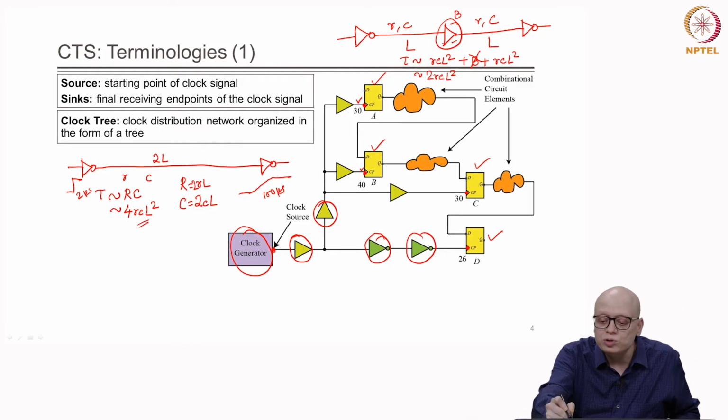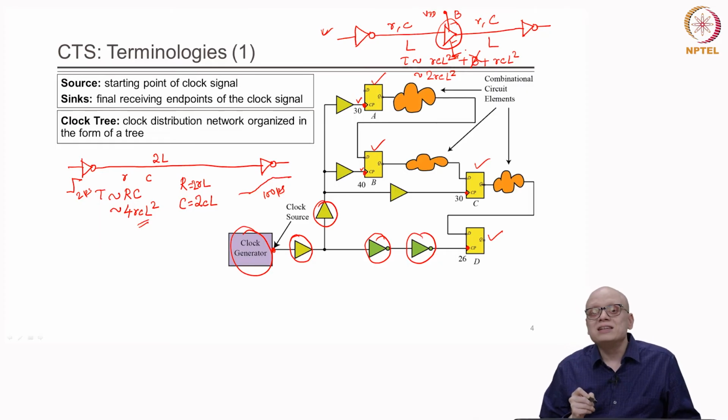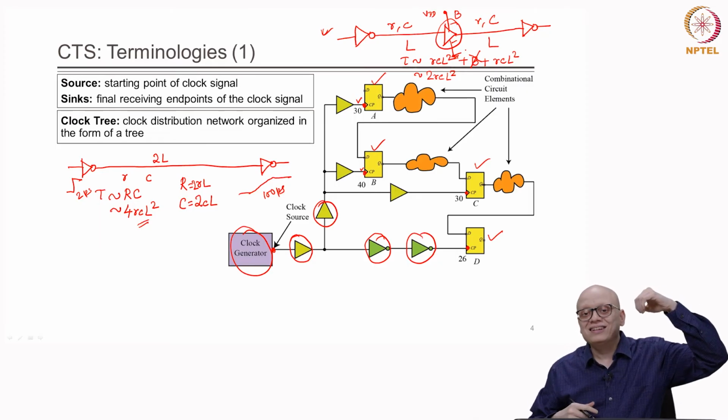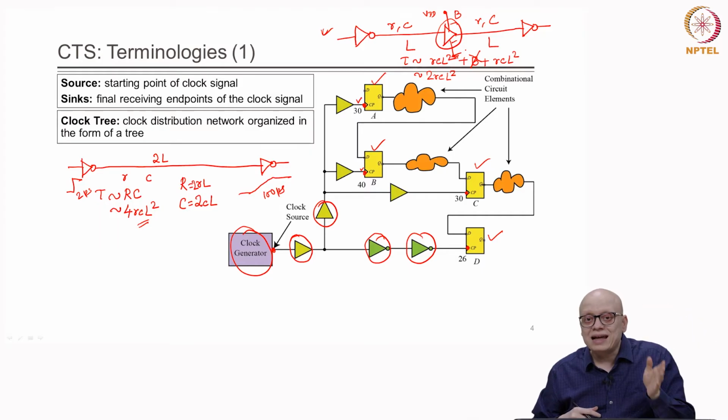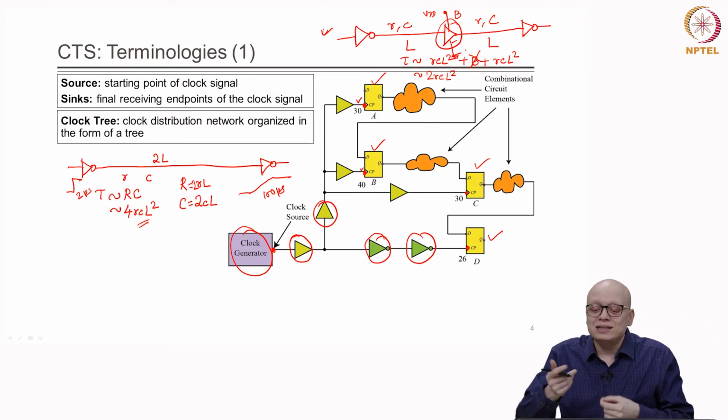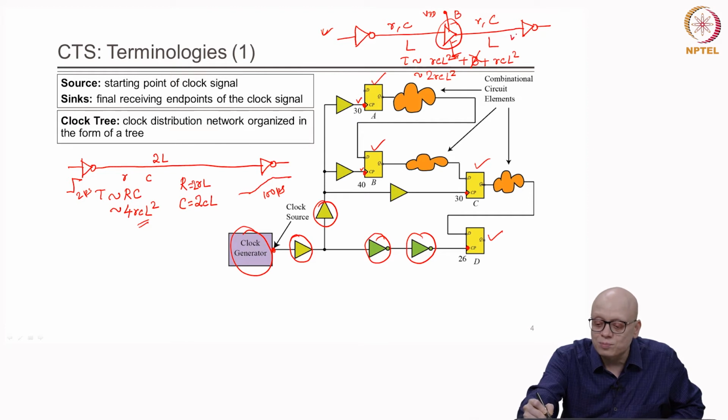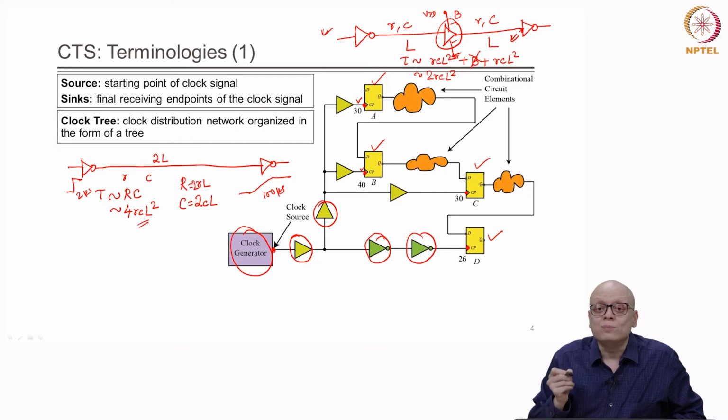Now, if we introduce a buffer in the middle as in the second circuit, in a sense these buffers will have VDD and ground lines also. So, this buffer is basically pulling up the signal to make it sharper, and as a result the quality of the signal that finally reaches the end point, the final buffer here, improves.